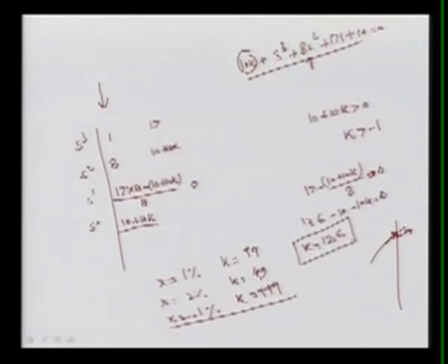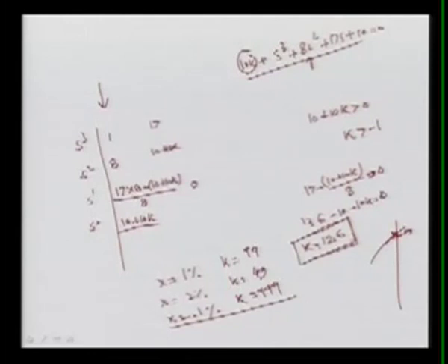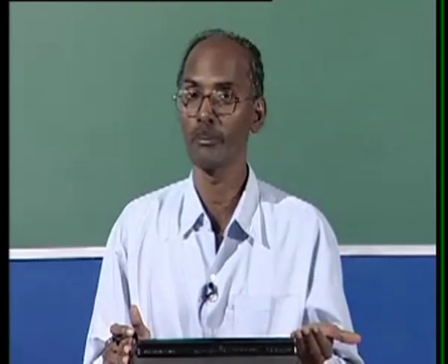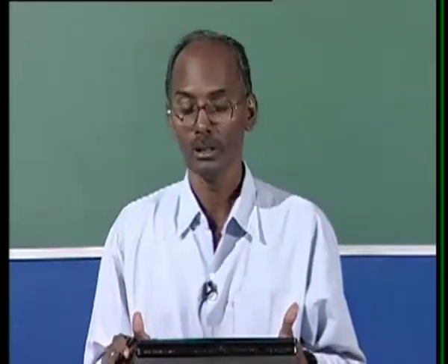So the time constant gives your dynamic response, and this value decides the stability. Means if you are increasing the gain more than this, you will no doubt get more static accuracy, but your AVR loop system will be unstable.